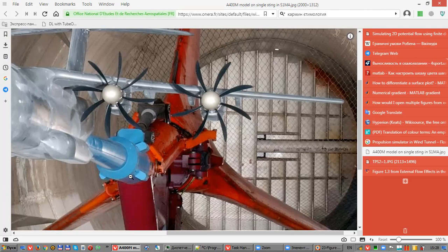This device is equipped with electrical strain sensors, and when forces act on this tube, the conductivity of this electrical sensor changes. So this device would be better than the one Antonov uses with wires. Maybe, but there are problems with temperature. When temperature changes, yes, there is a necessity for calibration. But this device is less influenced by aerodynamics.